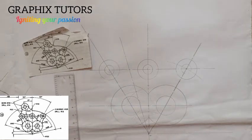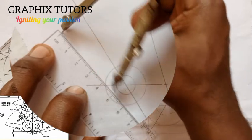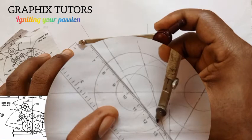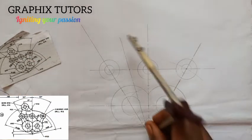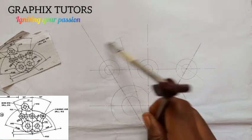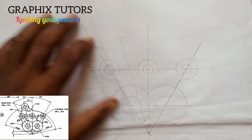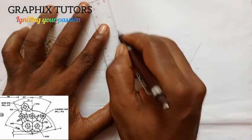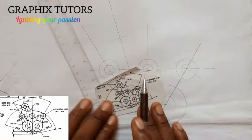To get the center. So let me measure the radius of 126 on my meter rule. So from here, if I place it this way, this is 0, this is 10, this is 120, this is 126 here. All good? So I'll just place it at the center here and strike an arc. It means this point here is my center of that circle. So let me just increase it a little bit. So this is what we have. That is where this circle will be located.